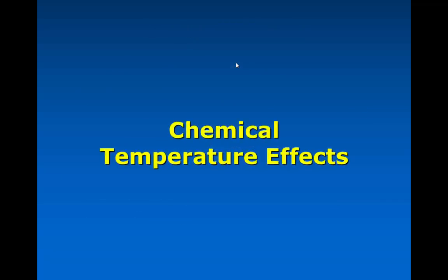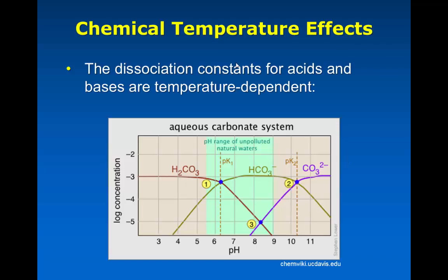Okay, lastly, we'll move on to the chemical part, and specifically here we're talking about the pH model. As you know, in GPSX, in the Mantis 2 model only, we do a full pH balance across the entire plant. And some of that pH model is sensitive to temperature. So I've put up this very simple carbonate system where we have the dissociation of carbonic acid.